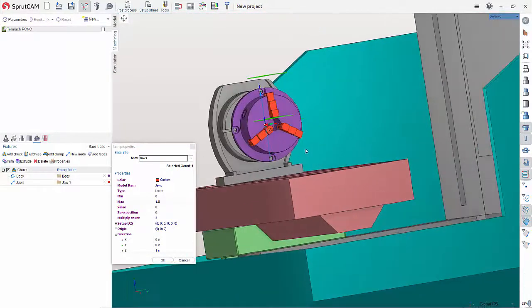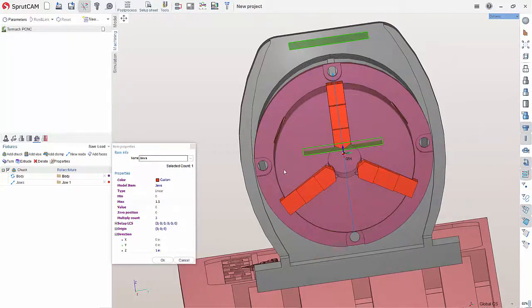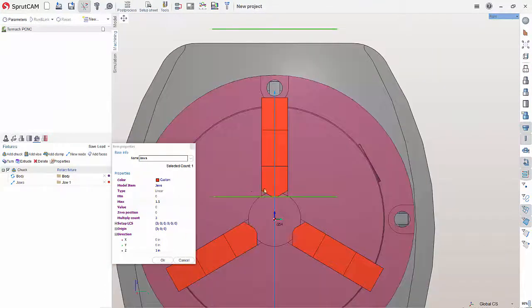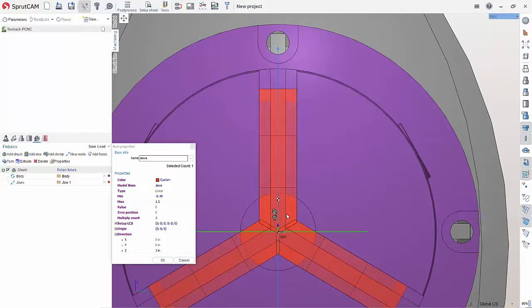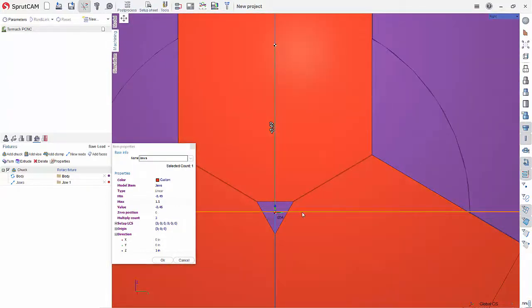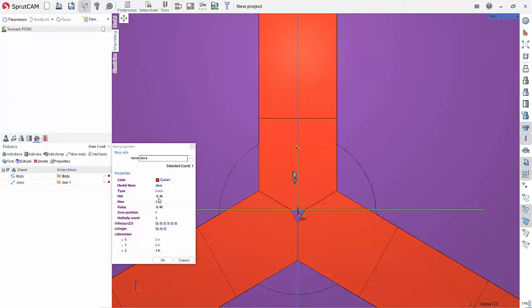And then we need to get the bottom here so these can actually join up, so you work with smaller stock. So let's just choose right view over here. This will make it a little bit easier. And bring this down. I'm just going to bring it down to 0 to test. Okay, now you can see they're going past. So let's bring them in so they're close together. And then for the minimum here, we can grab this green and bring it up to right about wherever we want. It looks like minus 0.46 is what we're looking for. So you could go in here for minimum and choose negative 0.46, and then we can hit OK.